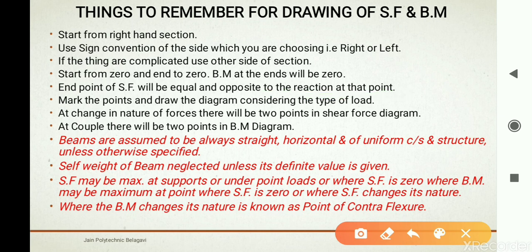Coming to the next point, mark the points and draw the diagram considering the type of load, whether it is a point load, a uniformly distributed load, etc. At a change in the nature of forces, there will be 2 points in the shear force diagram.